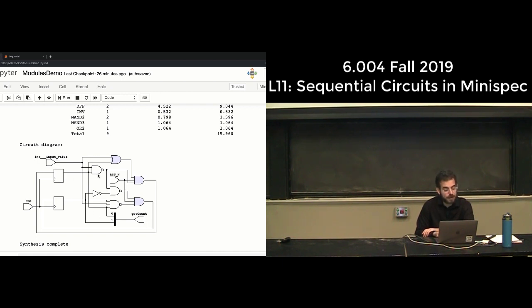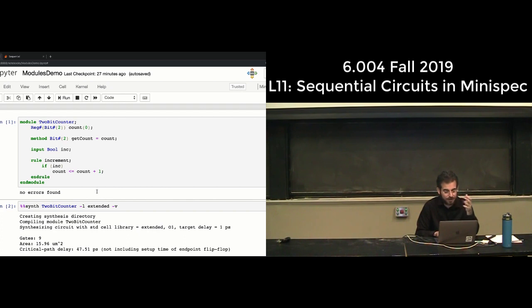And then you have this increment input and the reset input, and there's a bunch of gates that, based on the increment input and the reset input, determine the values at the inputs of the flip-flops for the next cycle, right? And of course, both flip-flops are driven by the clock signal. Now, you see that there are two inputs that don't show up in the code, and these are the clock and the reset. And that's just convenience, right? We're going to have circuits with clocks and resets, but you're not going to see these in the code. There's no clock input here. It's automatically generated.